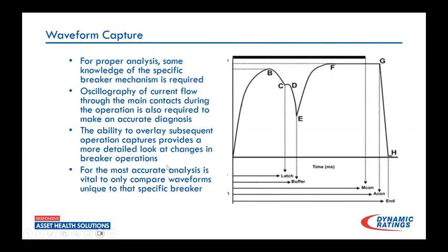Also, for proper analysis, and this is something we'll see in some upcoming slides, you do need to have some knowledge of how that mechanism's working. As I said, the latch is not always going to be apparent in the waveform. Sometimes you might be hitting something that actuates the latch and it's not actually striking the actual latch to pull it. So things like that, to understand what you're looking at, is going to help you go a long way towards making an accurate diagnosis of what you're seeing when you do run across a problem.